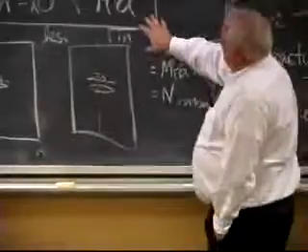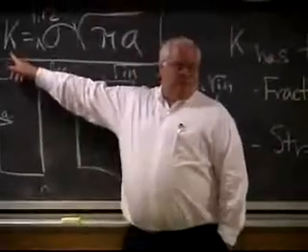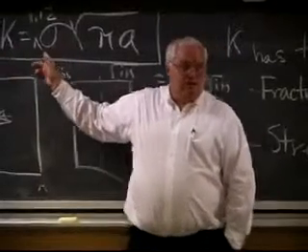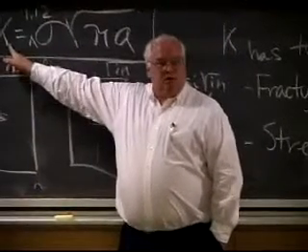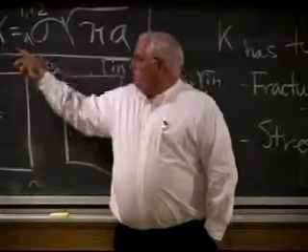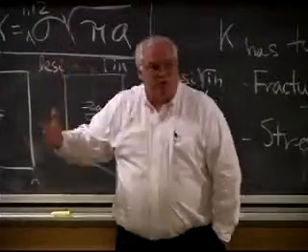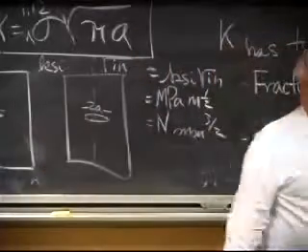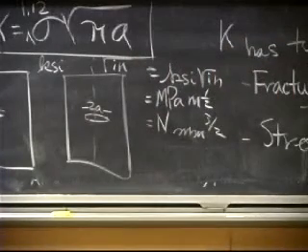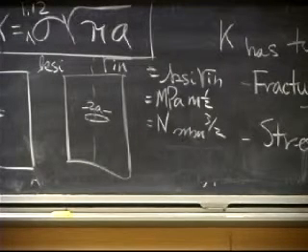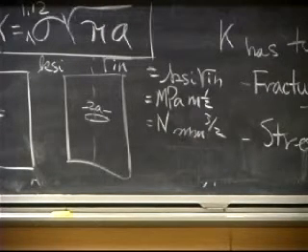I didn't even have to go to a gigahertz computer to do that. If, on the other hand, this is 100, and I apply a stress of 50 KSI, that's 2. If I square, and K over sigma is 2, I square 2, I get 4, I divide by 3, the critical flaw size is 1 1/4 inches. That's a metal. Critical flaw sizes are on the order of inches, unless I'm talking about really, really high strength metals, like aircraft landing gear, where the fracture toughness is like 300 KSI or something.